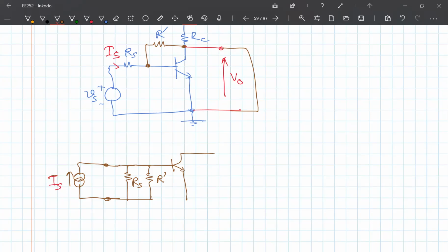Okay, so to find the output circuit, what we do is basically short circuit the input, so Vi is set to 0. That means it is like that. So once you have that connection, in order to find the output impedance, you have the output circuit. When you short circuit this, there is no current going into the amplifier because the whole current will be short circuited through this shunt, right? So therefore there is no input current, so therefore there will be no output.